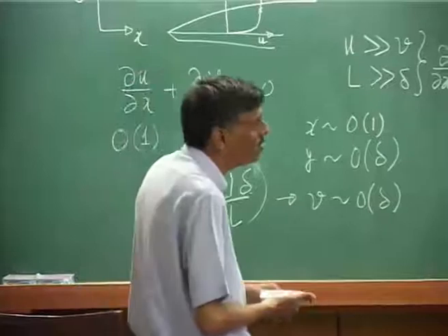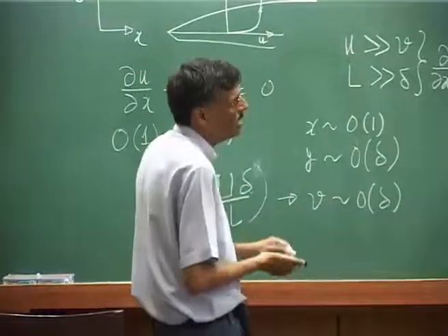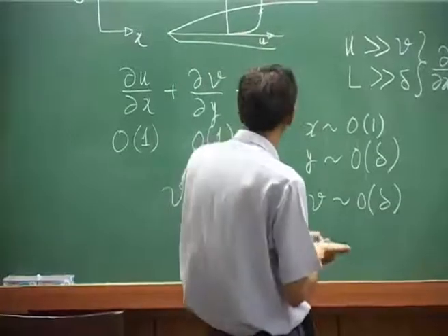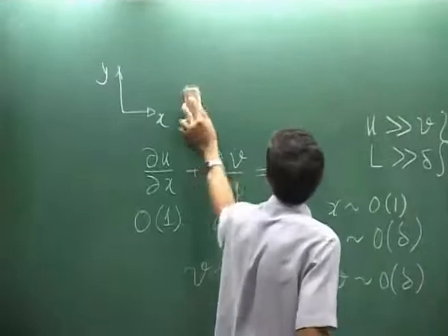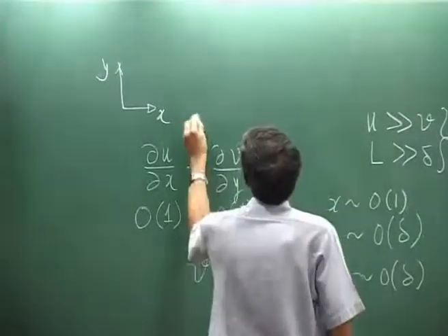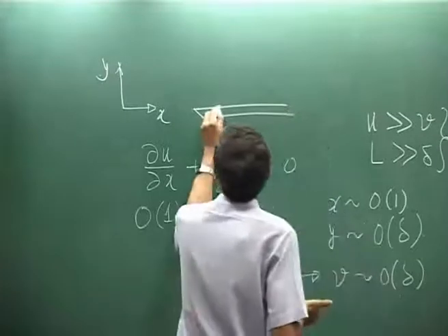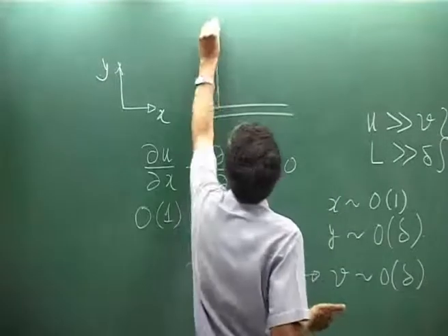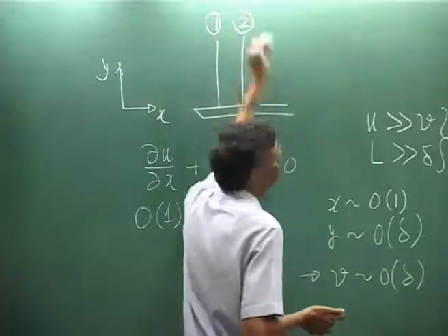An initial value problem, or a marching problem, is something like this: if I look at this boundary layer growing over this plate, the equation allows us to get the solution in station 1, then I can get the solution in station 2.